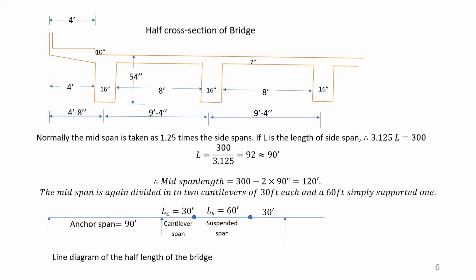As you know, maybe you have learned in earlier courses that previously the minimum slab thickness was 5.5 inches, and nowadays as the loads are heavier, they have come to this 7 inch minimum thickness of slab.